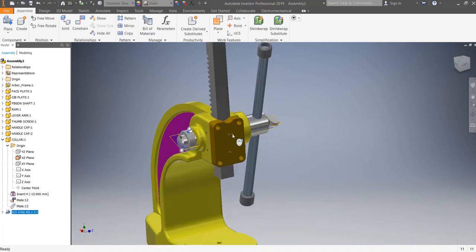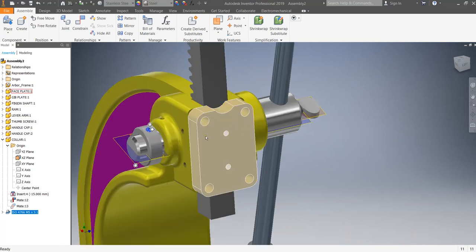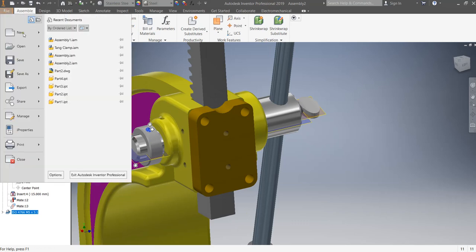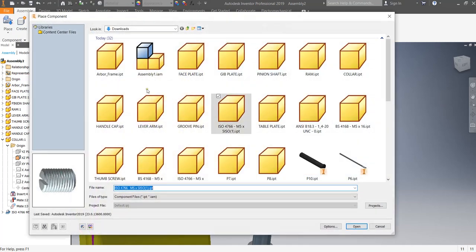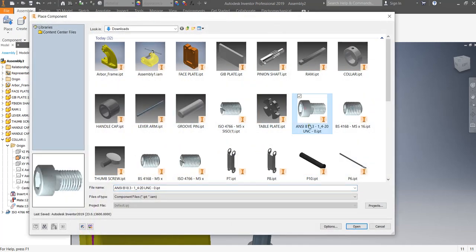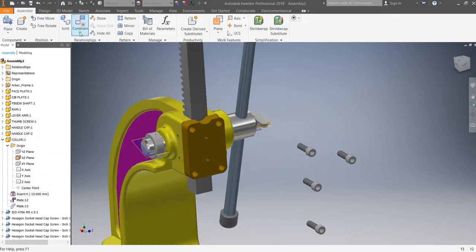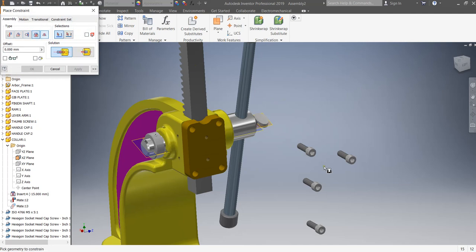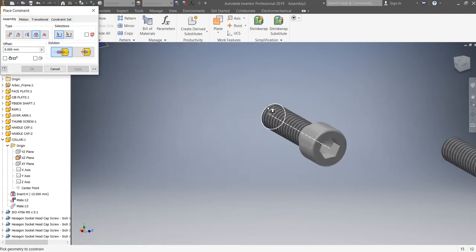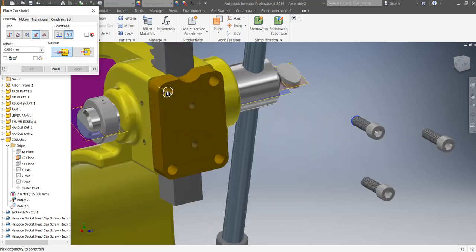Next we have to place these 4 holes, screws, and here also. So I will go to place again. These we need 4. 1, 2, 3, 4. Again, the best thing, insert, I think. So I will make insert. I want to insert this screw so that this circle and axis mate with this circle and axis with, say, -30 offset. Again, we should know the exact distance.